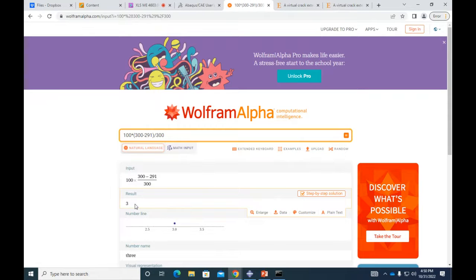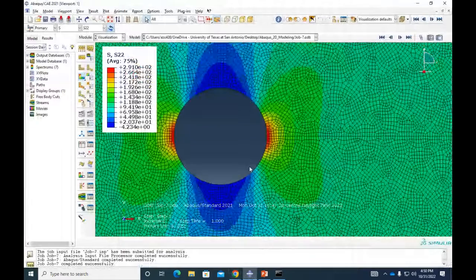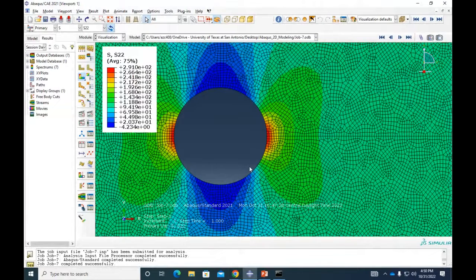For your cases, you don't have known solutions, right? You are just doing an analysis. So what you can do is try your mesh, try to super refine it, and then see if you see some important differences. If you see that the stress changed from 50 to 75 megapascals, that means that your problem is still sensitive to the mesh that you are using, right? Here, I think we have reached a point where the problem is insensitive to the mesh. If we keep refining the mesh, the solution is not going to get a lot better. So we can stop there.